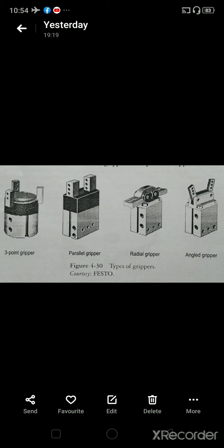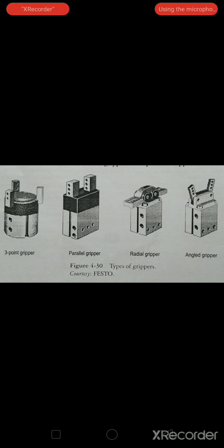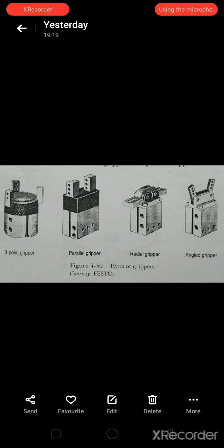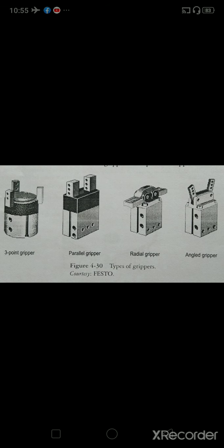Likewise, the grippers are usually fitted with at least two sensing slots for sensing the jaw position. It is possible to block the gripper exhaust air so that the gripped workpiece is stopped from being dropped from the gripper fingers in the event of a compressed air failure. The important characteristics of grippers are low cost, high gripping force per torque, and precise centering.